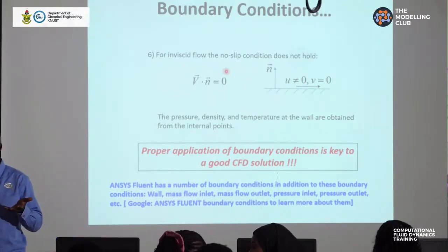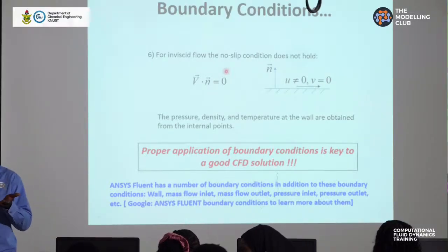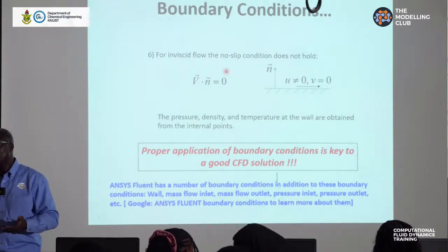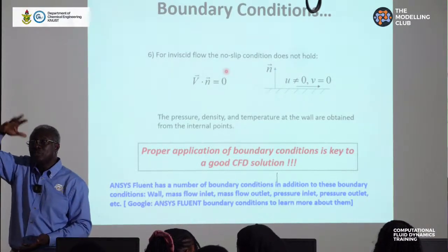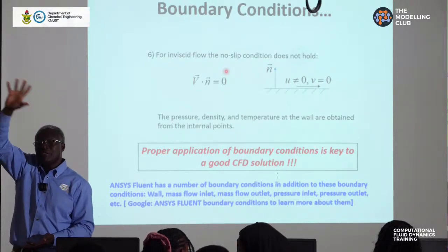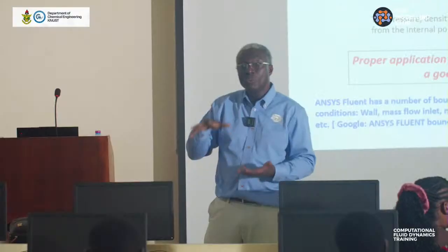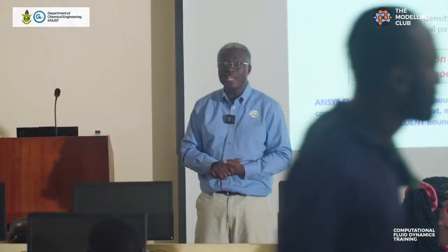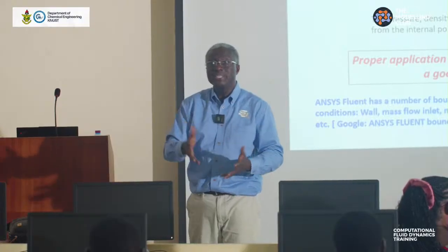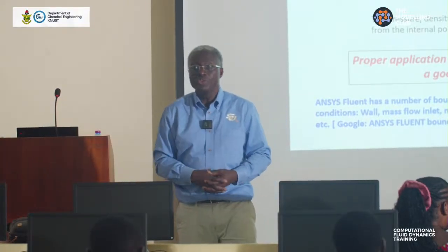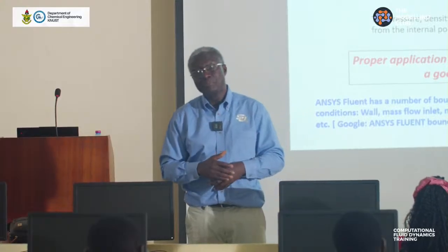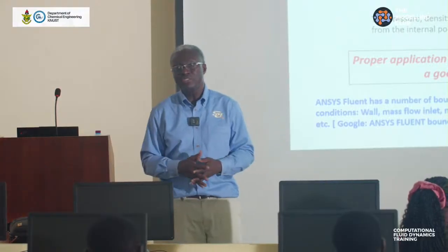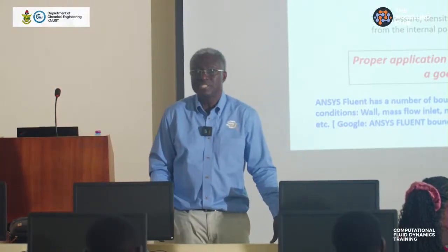And anything above it, well, it's open to the sky. And we know that far away from the aircraft, those boundary layer effects, those environmental effects will not impact the aircraft. What impacts the aircraft most will be the fluid in immediate contact with the aircraft. And so that is what you have to consider most important. But you cannot say that there are no boundary conditions in solving the Navier-Stokes equation. You always need boundary conditions.